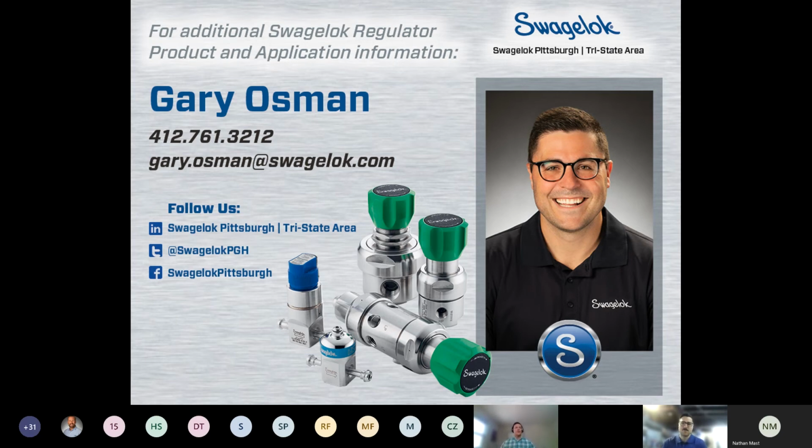Differential pressure regulators allow users to reference a point in the system. A good example might be a dry gas seal on a big piece of rotating equipment. Very often that seal pressure needs to fluctuate with whatever's happening inside that piece of equipment. One of the ways to do that is to use a differential pressure regulator. You sense the pressure wherever you want to reference it.